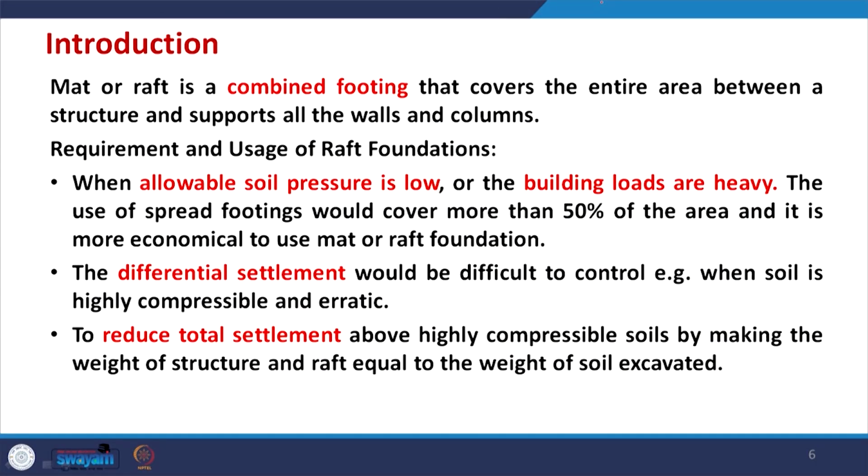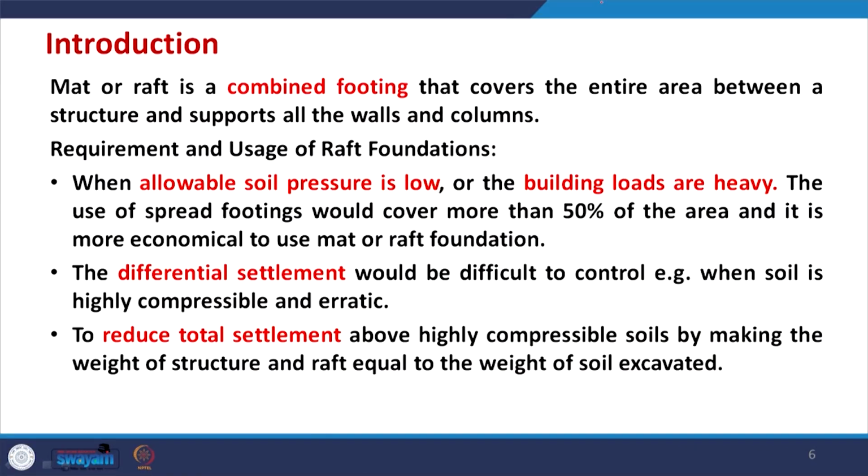What are the requirements and uses of raft foundations? When the allowable soil pressure is low and the building loads are heavy, it is recommended, even without an earthquake, that one should go for a raft or mat foundation. In this case spread footings would cover more than 50% of the area, and it will not be economical to use spread footings; it will be more economical to use a mat or raft foundation.